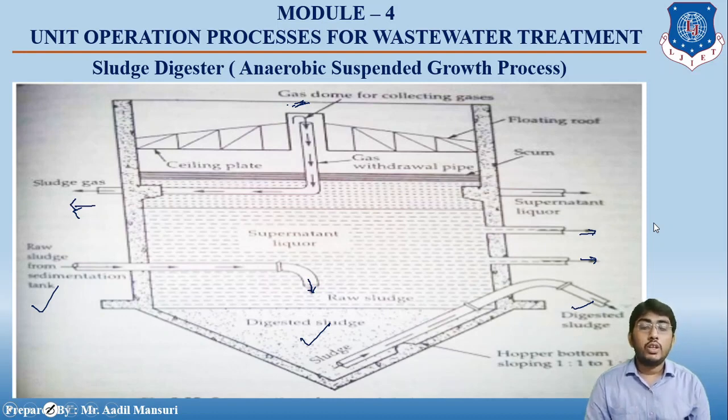Low molecular weight fatty acids are the intermediate product of anaerobic biodegradation, and these acids are known as volatile acids because they can be distilled at atmospheric pressure. Acetic acid, propionic acid, butyric acid, and up to a certain extent valeric acid, isovaleric acid or caproic acids are the important components of the anaerobic biodegradation.